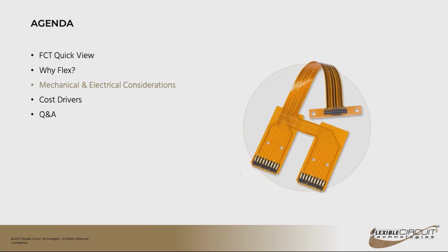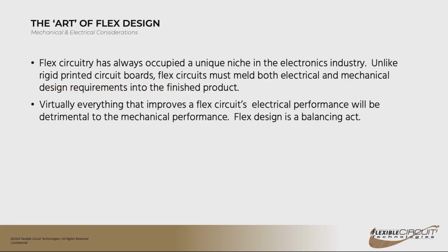Now we're going to look at electrical and mechanical specifications and requirements that will be needed on your flexible circuit design and how each of those requirements can impact other requirements on your design. Flexible circuits are unique in that, unlike a rigid printed circuit board, they have to be able to fulfill all the electrical requirements of the application, but in addition, they have to be able to bend and fold.